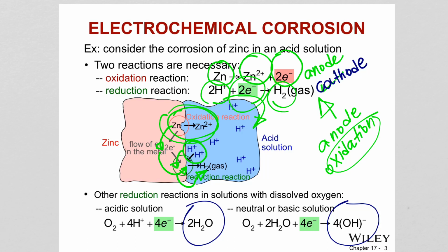So these ions have to be carried in a liquid environment. So if these three things are not present, then you cannot experience corrosion in your part. Okay, so three things: anodes and cathodes must be present, anode and cathode must be in electrical contact, and the liquid environment must serve as an electrolyte.